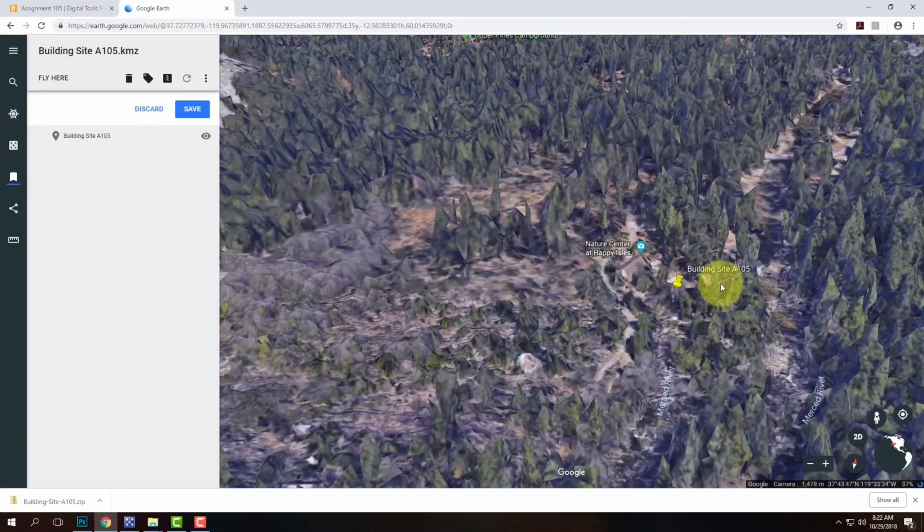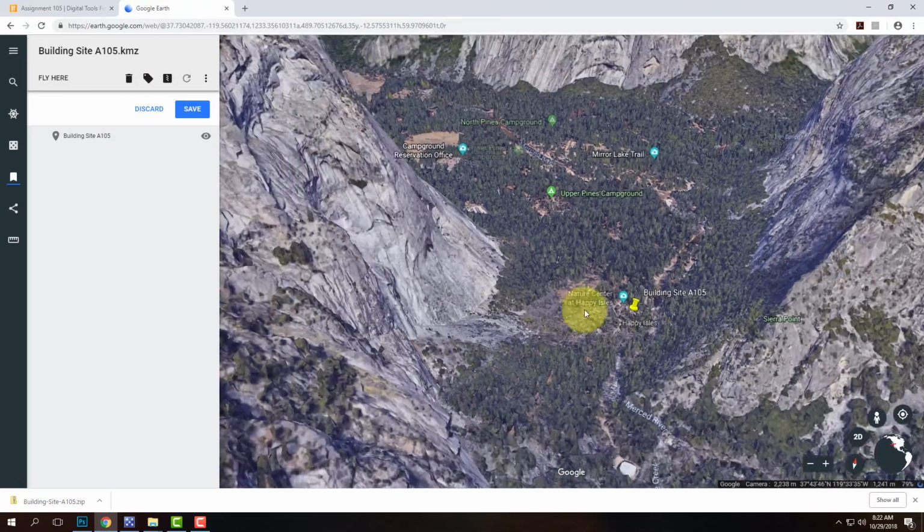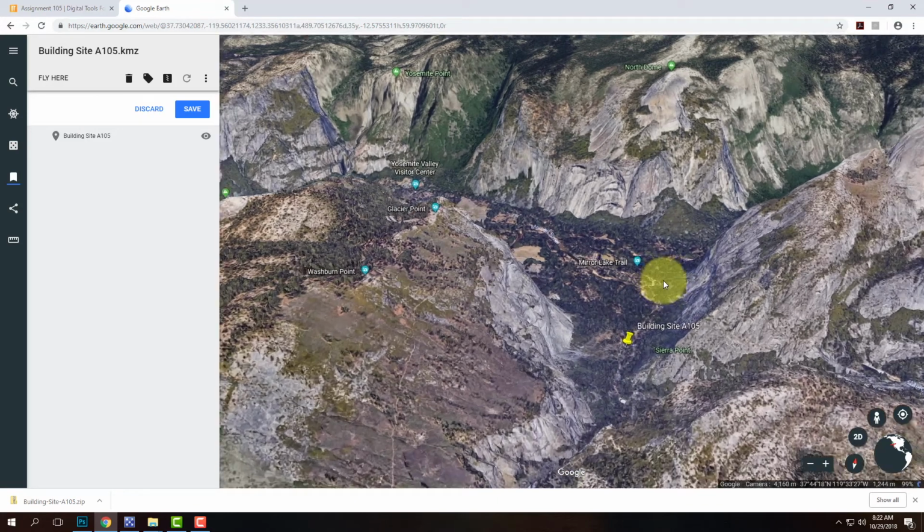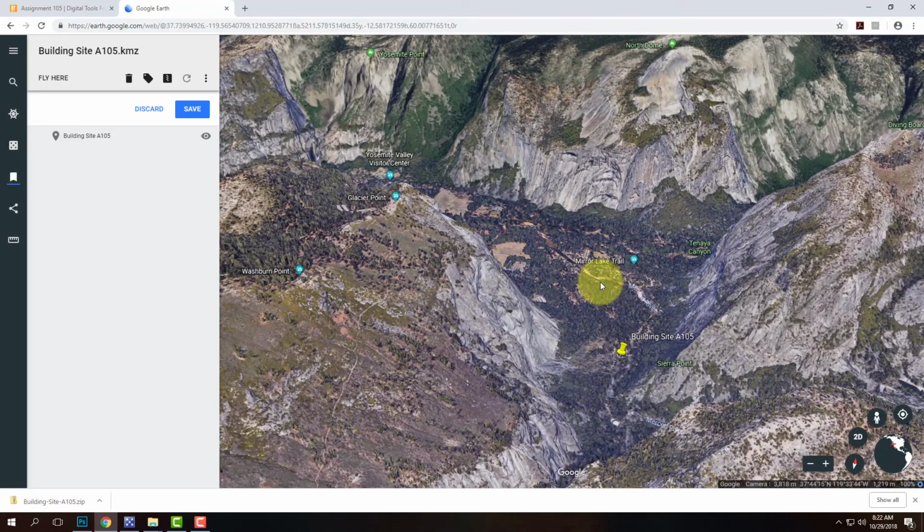It's a wooded portion, so there are some trees around where our building site is, and we have the mountains on either side. That means a couple things. One, in terms of sun, this is the site analysis part that I'm talking about. Part of it is just viewing the site and seeing what's around here. But the other part of this is thinking about what's happening on the site in terms of climate, etc. So we're not going to get a huge portion of light during the day because we're surrounded by these large cliffs on either side. So our direct sun is going to be rather limited on this site. We're going to get it a little bit later in the day, and we're going to lose it a little bit earlier in the day as the sun starts to set.